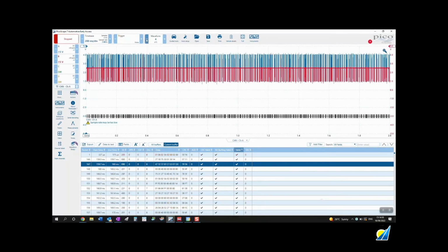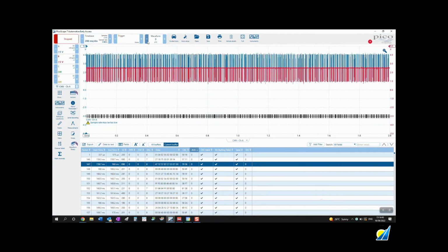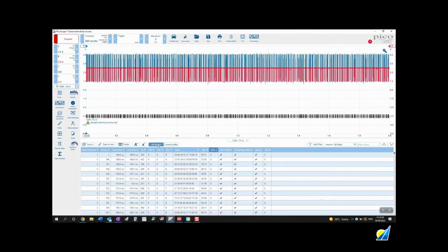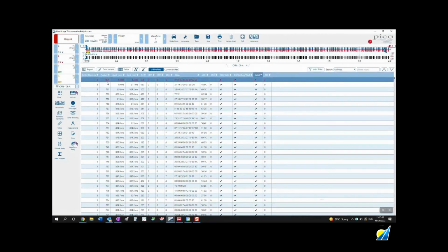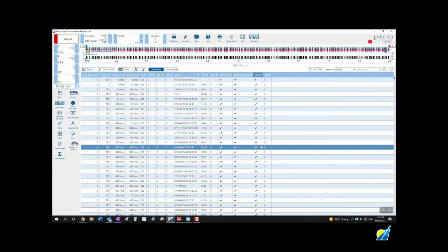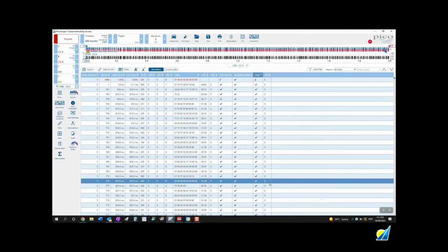So this is now decoding for buffer 4, and if we decode on valid, any failures to acknowledge? No, that's all good. Let's go back through them all. In fact, if we go all buffers, this will present us with the entire buffers, all 5. And let's look for valid. There's 1, and it was that one there again. So the only one that failed through the tap test of the instrument panel was the one where we'd stopped the capture midway through the packet.